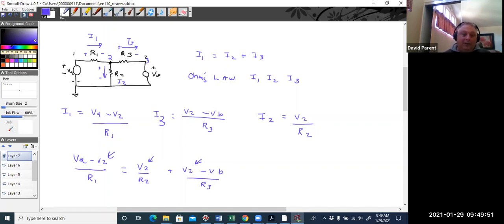Then I would short this one, notice R2 and R1 are in parallel, and then do a voltage division, and then sum up the two resulting things. So that whole superposition thing wasn't just some extra thing to learn. It could be a more intuitive way of doing your circuits.